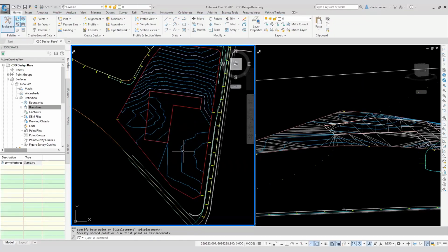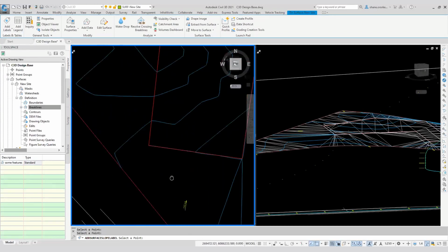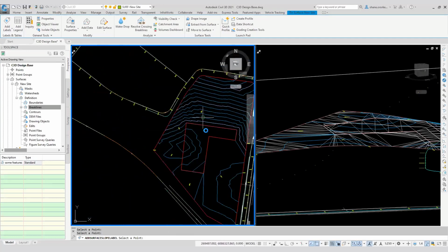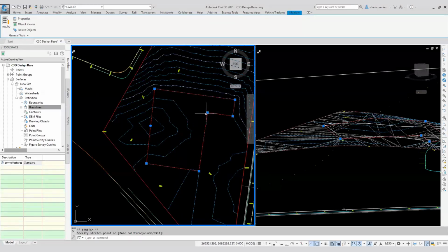Okay, you can put on some slope arrows here to assess what sort of slopes you have. And if you want some information here about how steep things are, this is quite a good tool to have a bit of a look at. But as I move the feature line around, if I hold down Shift, I can grab two groups at once, move them as a collective. But basically, as you ooze that shape out, you're changing the terrain underneath.